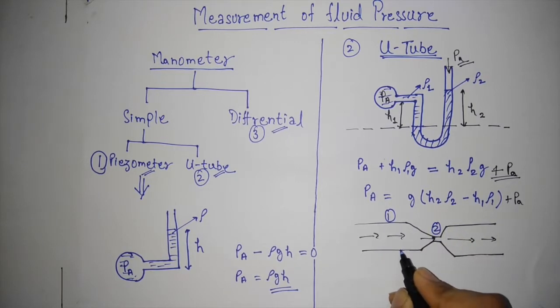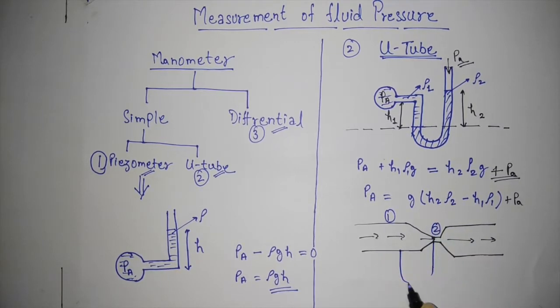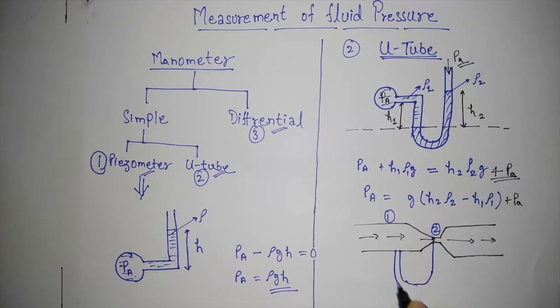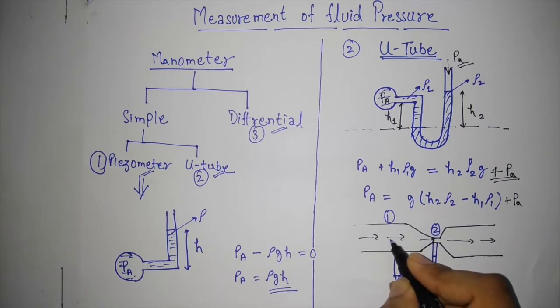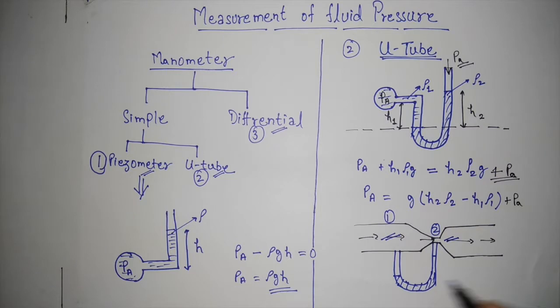So a U-tube manometer is inserted between these two sections, and a manometric fluid, generally considered as mercury, is used in this manometer. Because of the pressure difference at section 1 and section 2, a rise will take place, which is measured as del Y, which is included in the calculation of discharge of water through venturimeter.